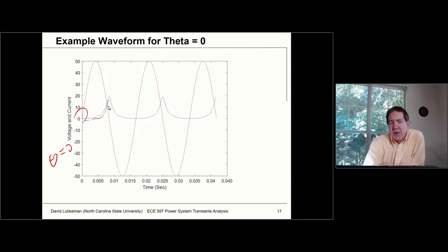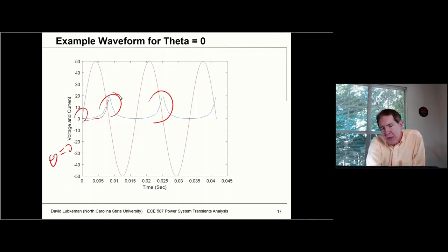And then as the flux drops off, it drops back down again. But we're basically going to see this cycling of current that has a DC offset, and it's just going to be changing every cycle as shown here. And then eventually what happens in a real circuit is these peaks start to die down and eventually go to 0. But the damping isn't such that we don't have to worry about what these peaks are.